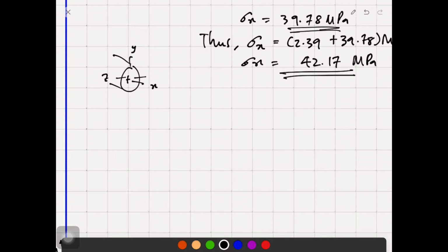So look at point E. We are going to have a look at that. This is the moment that we have in the x direction, right? Transverse shear. I try to explain this again and again. This is your neutral axis, and the stress profile for transverse shear is always parabolic, maximum on the neutral axis and 0 at the location of the outer skin. This is opposite with bending.